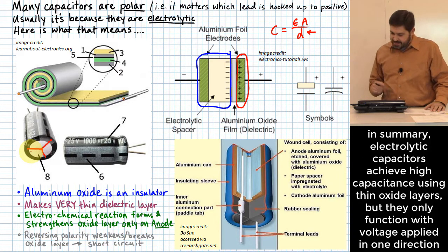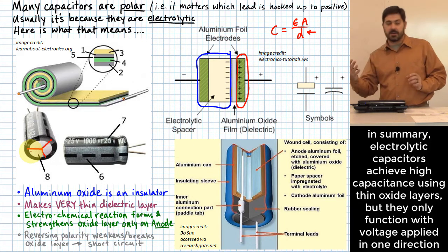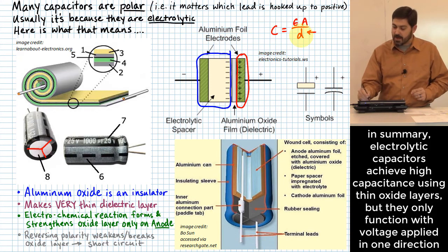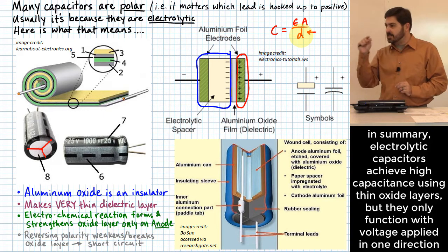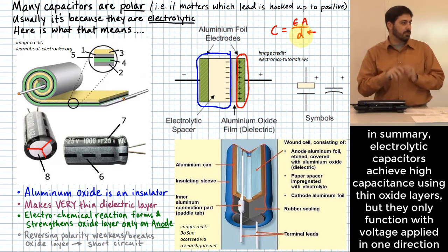All right. I think that's about all I have to say about electrolytic capacitors, but it's interesting stuff. They are a good way of getting a high amount of capacitance in a fairly small package. And again, the main reason why is that low value for that distance between the two conductive plates that form the capacitor.